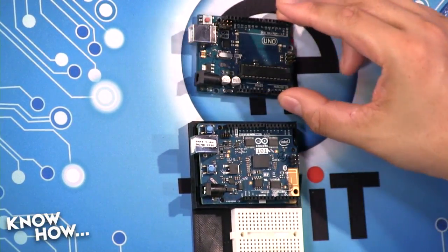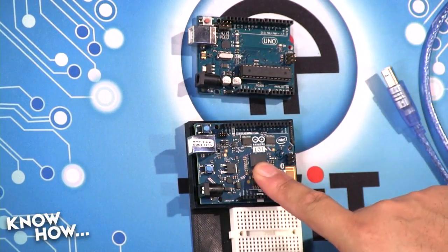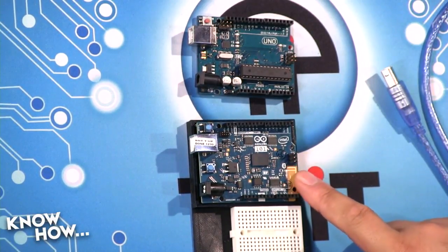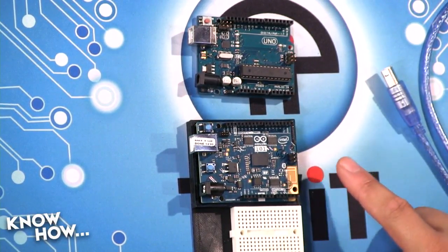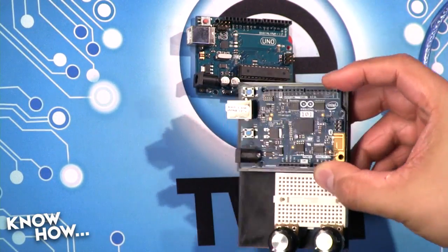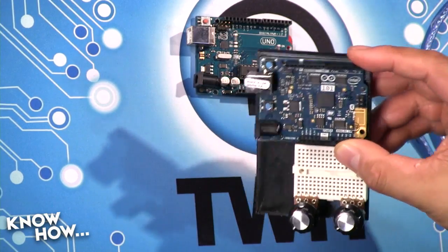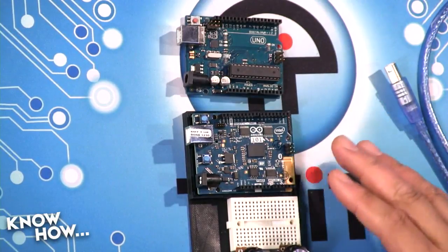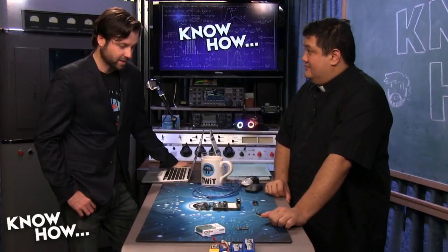So why would you use this Intel one over the Atmel? I'm glad you asked, Brian, because it's not just the same kind of pins. You have Bluetooth LE, so low energy Bluetooth, so you can use this as a beacon. Integrated, that's what this antenna does. And there is a 6-axis IMU, a gyroscope, so it allows me to use this like a flight controller. It will be positionally aware. It knows where it is, and it can wirelessly communicate to other devices without me ever having to plug anything into it. I like that idea already.